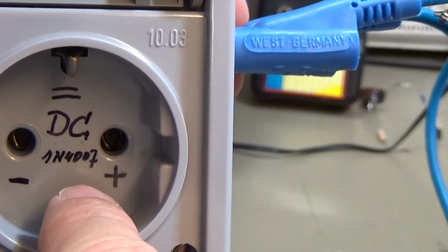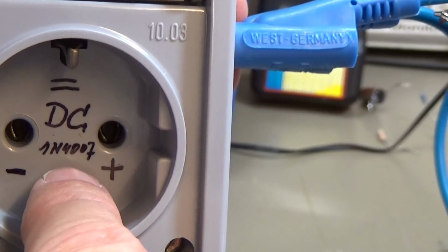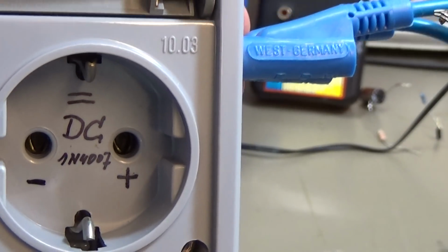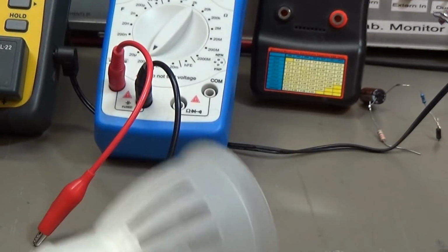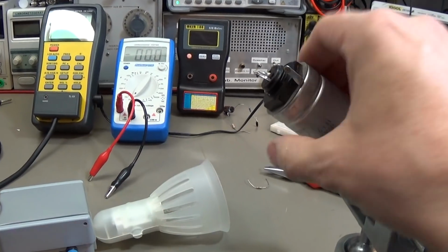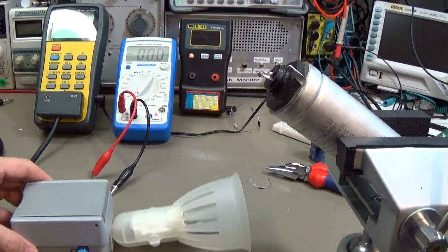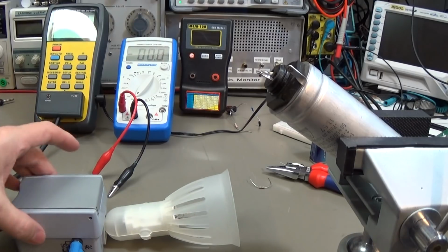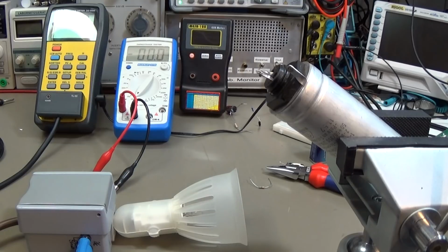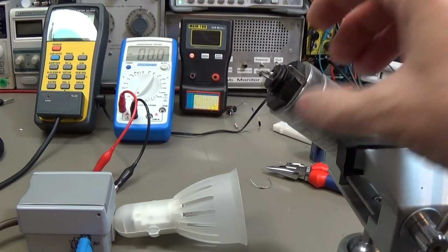And you see I've written it in. It is a 1N4007, so that is our rectifier diode. And if I have a very old capacitor like this here, I can always reform a capacitor so that it is back working fine, and that is what we want to do now as well, because we want to know if